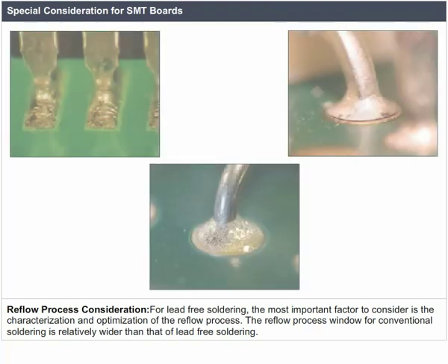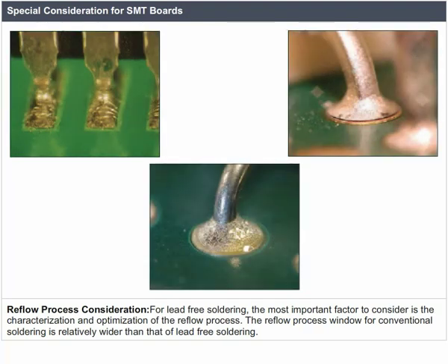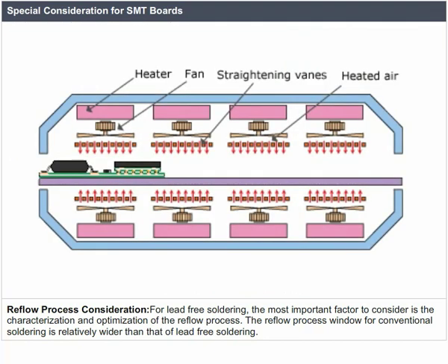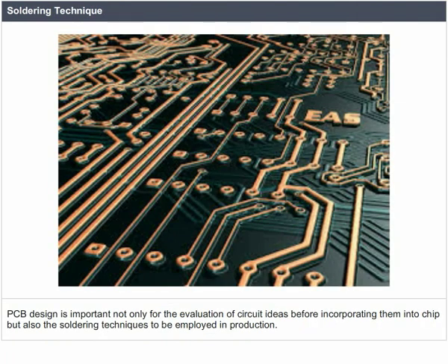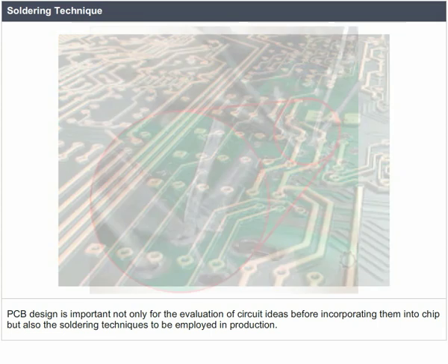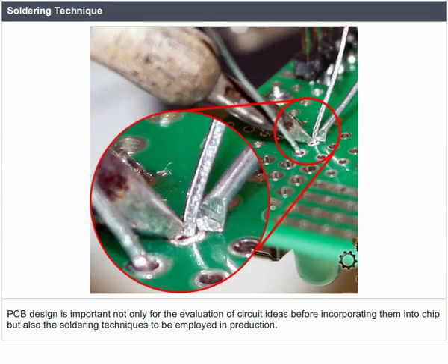Reflow process consideration. For lead-free soldering, the most important factor to consider is the characterization and optimization of the reflow process. The reflow process window for conventional soldering is relatively wider than that of lead-free soldering. Soldering technique. PCB design is important not only for the evaluation of circuit ideas before incorporating them into chip, but also the soldering techniques to be employed in production.